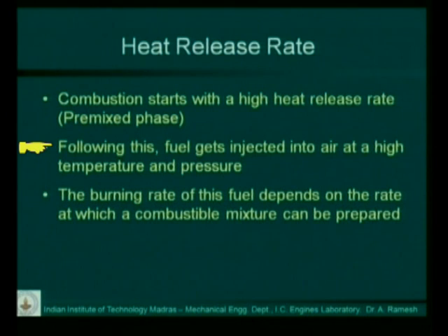So if you look at the diesel engine, the first portion of heat release after the ignition delay is called the premix phase, and in the premix phase, combustion starts with a high heat release rate. That is, combustion is sudden. And following this, the fuel gets injected as the burning occurs, and the temperature and pressure further go up, but combustion is not so sudden. It's not so rapid. And in the second phase, the burning of the fuel depends on the rate at which you can mix the fuel and air. So I believe all this is already known to you. So I'll just come back to this.